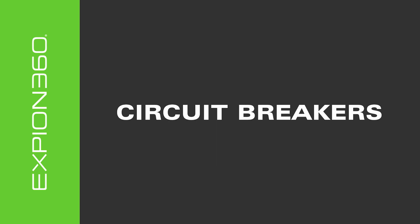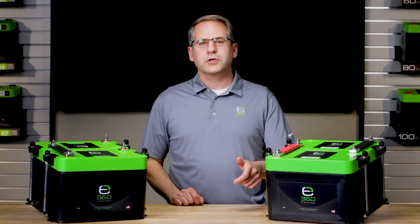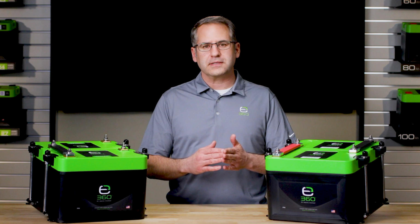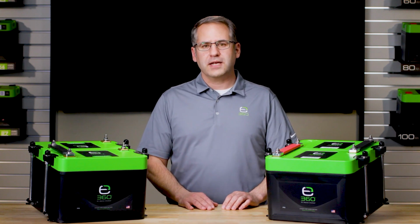The final category of circuit protection is circuit breakers. A circuit breaker is described as a switching device that has the ability to interrupt a circuit when an overcurrent or short circuit event takes place. This can take place automatically or manually, but its basic function is to interrupt a circuit flow after it has detected a fault. Circuit breakers are used in both alternating current and direct current circuits, but they are designed specifically for either AC or DC. They are not meant to be interchanged.